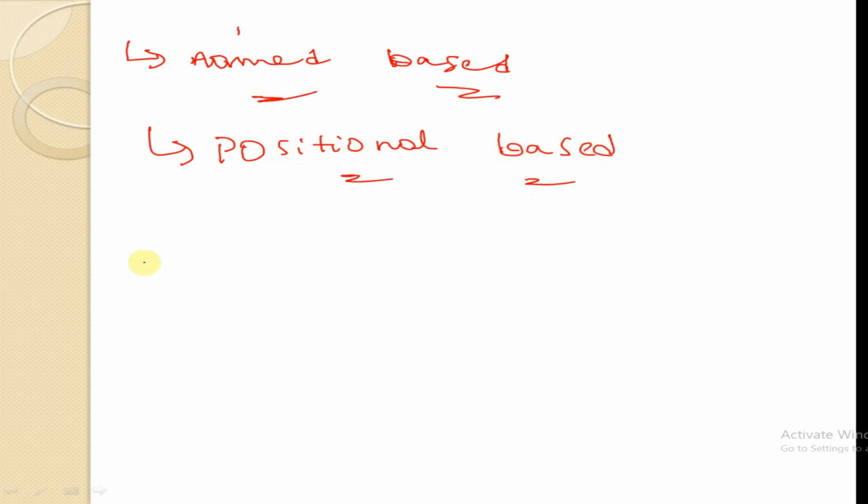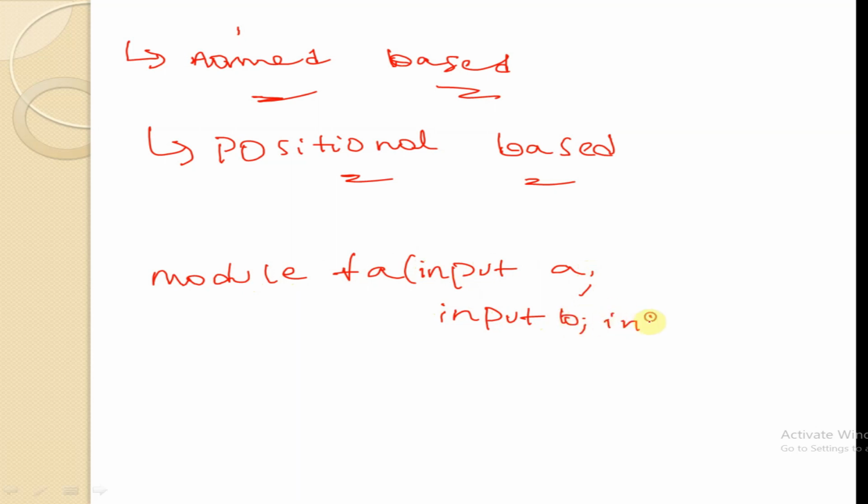So for example, let me declare some module, module full adder, input A, input B, input C, and output sum, output carry.